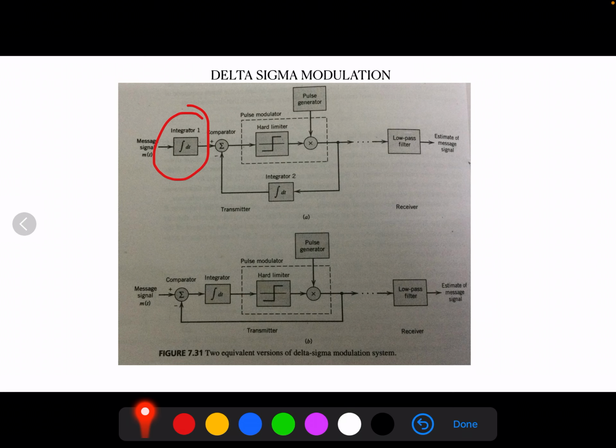The reason for investigating delta modulation is its reduced bandwidth requirements when compared to the PCM. For telephone applications, a typical PCM may use 8 kHz sampling rate with an 8-bit representation for an overall binary symbol rate of 64 kHz. As we have seen, delta modulation uses 1-bit representation but oversamples the signal.